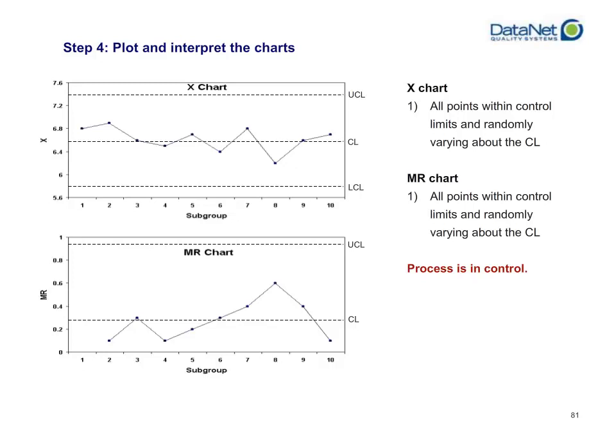From what we can tell from the X chart and the MR chart, there are no points that are falling out of control. Therefore, the process itself is in control. Now, that's not to say that there might not be something you want to investigate. If you had your own set of control rules that you wanted to follow or something that you wanted to recognize, having this plotted out in a control chart, you can still begin to see patterns, but in the strictest sense from how you calculate control limits, all points are within control and are randomly varying about the center line,